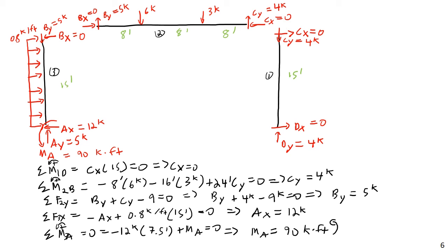Now, while you write that down, I wanted to go back and talk about this a bit. One thing I really like about these examples is that it really gets at the heart of the relationship between member internal forces and end conditions. In other words, if you really want to know something about a member, know how it's supported, know what its end conditions are. Once you know the end forces, the end moments and the axial forces, and what loads are applied to the outside of it, you can very easily solve for all of the internal forces. The real difficulty in frames is solving for those member end forces. But once you have those, everything else is fairly straightforward.